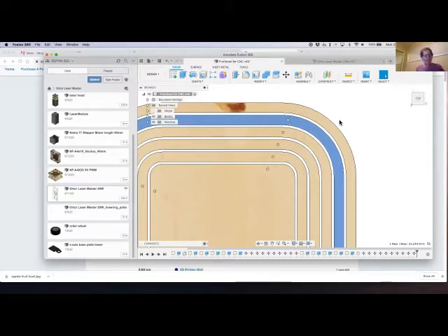And I did DXF. Well, I tried a little bit of everything. That was your export, but then you imported into vCarve, which is really like a 2D carving thing, right? vCarve will take in a 3D model as well. And the challenge when I use a 3D model, first of all, it would run the slot twice because it did both sides of the slot, which just took up a lot of extra time. Not a big deal if you have one at home, but it is a bigger deal when you have a 3-hour time slot at the member shop.